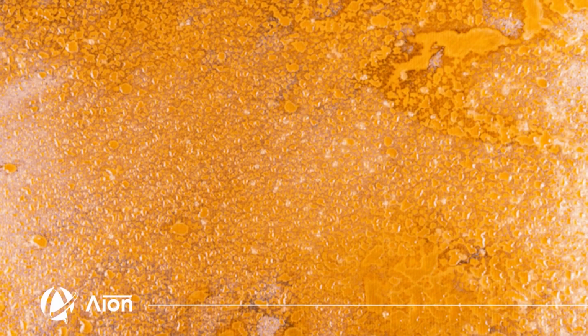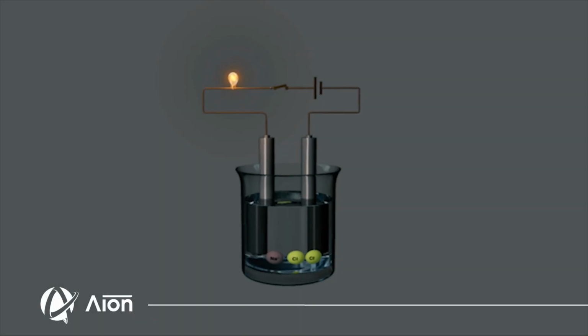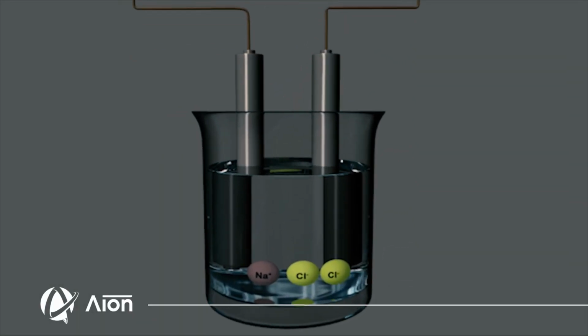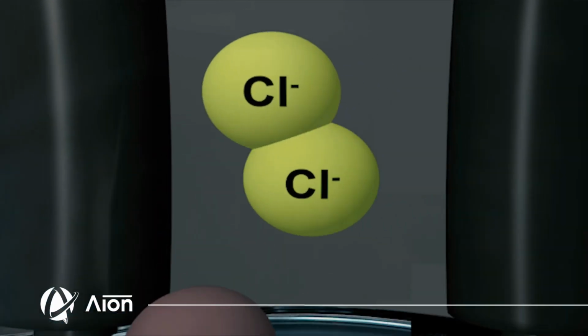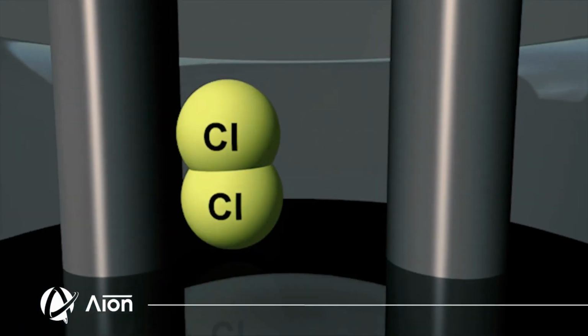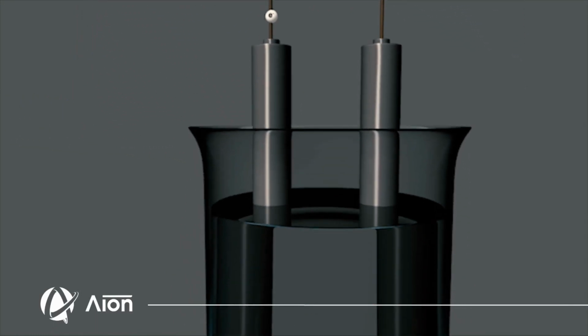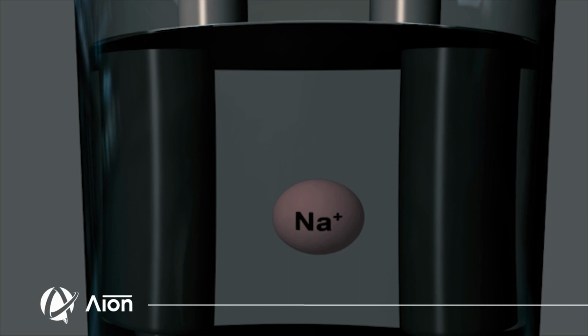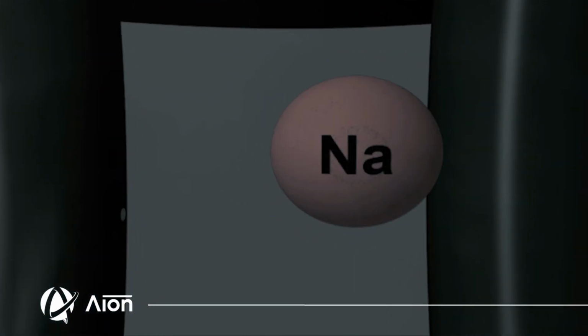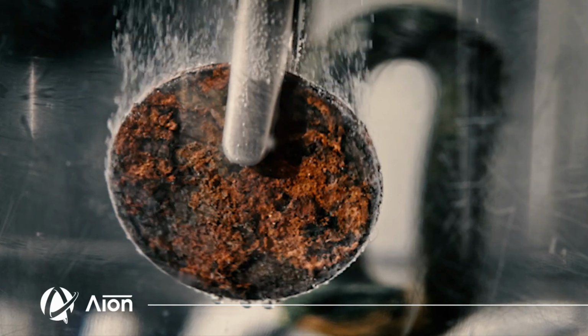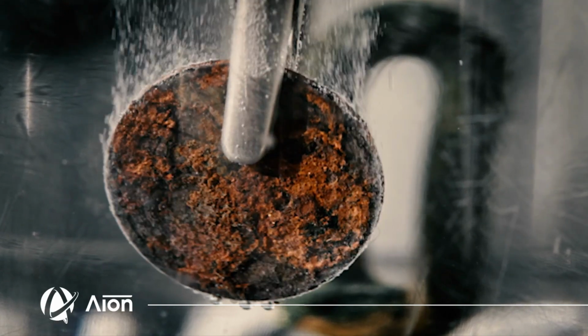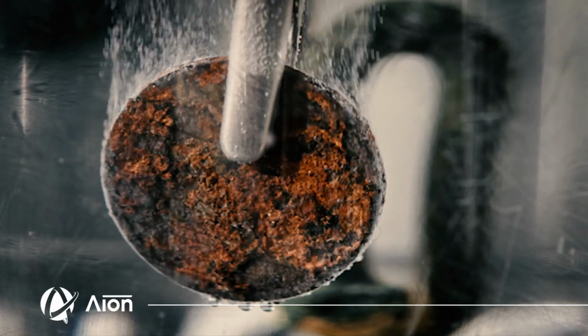Corrosion is an electrochemical process, essentially a chemical reaction that functions akin to an electrical circuit. It involves two distinct steps: reduction and oxidation, occurring at separate locations. The conductive metal allows for the flow of electrons from areas of low electric potential, known as anodes, to areas of high potential, known as cathodes. As electrons move, the anodes lose electrons and undergo corrosion. Interestingly, even within the same piece of metal, different sections may possess slightly different charges, fueling the corrosion cell.